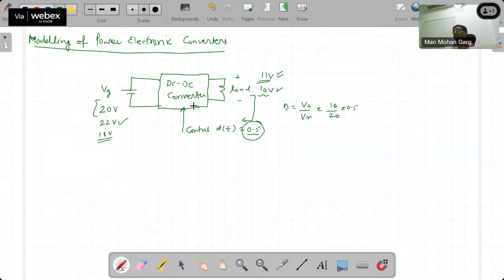Now this model, if it replicates the physical system as accurately as possible, then what will happen? I can play with these mathematical equations, with these mathematical models, and I can design hundreds or thousands of controllers for that. Whichever controller works fine with these dynamics, I will say, okay, I will go with this. Then I will make a small prototype of that system and implement the designed controller over that. If it is giving me satisfactory results, then I can dare to implement the same thing on the actual plant, right?